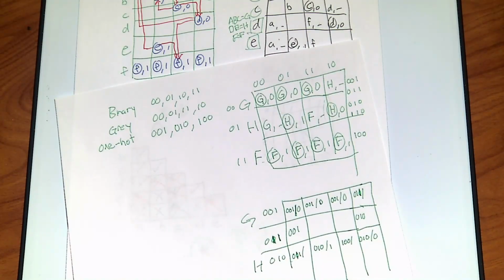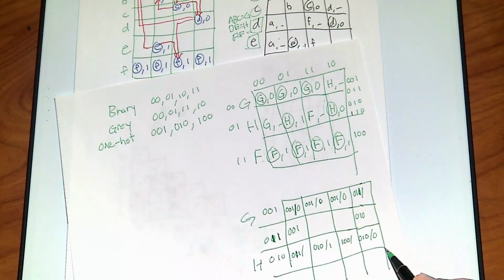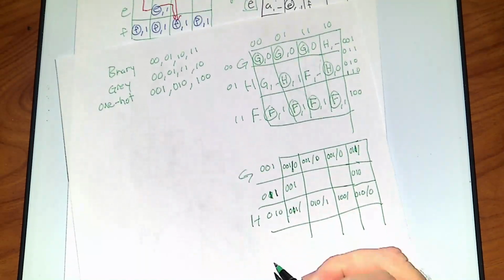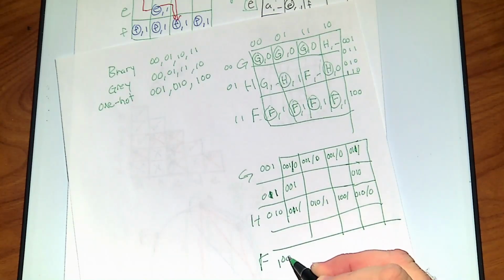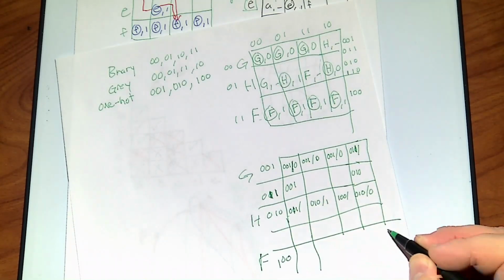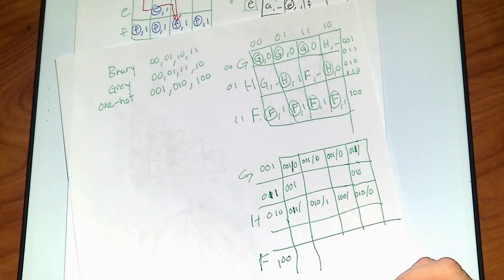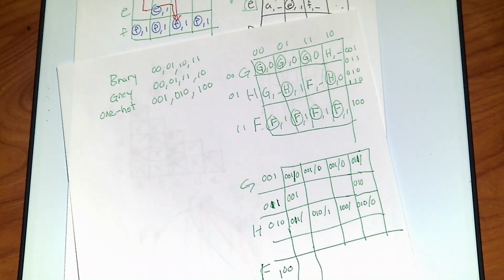Now, in this column, if I go to any other row, when I'm going between 2 rows, there's no ambiguity, and that's the only way I can get to this middle state. Once I add some other state in here, if it has a transition in any common column here, then I'm in deep trouble. Because if everybody's going to 0, 0, 0, you don't know where you came from.